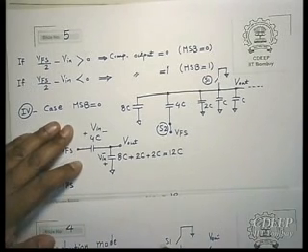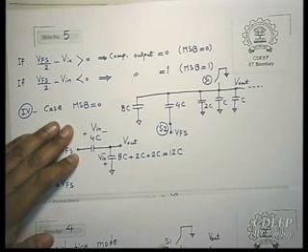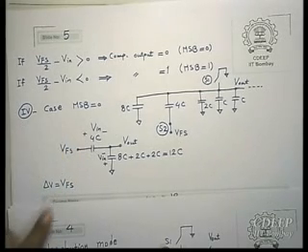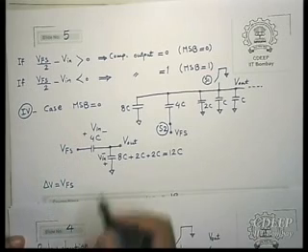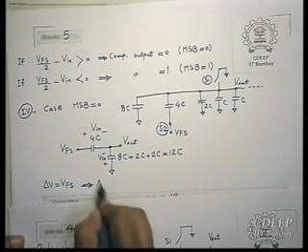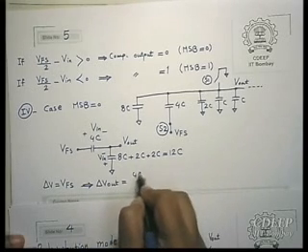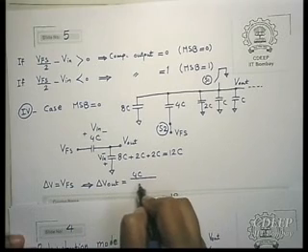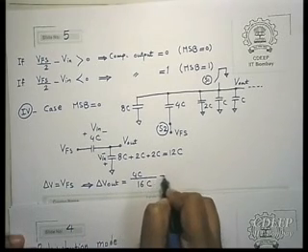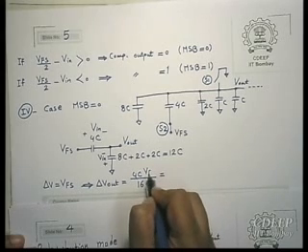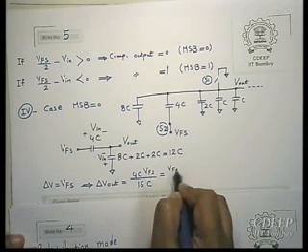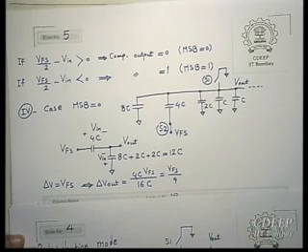Therefore, when you connect it to 0, the initial voltage has been 0. Now you are changing it by the amount of V full scale. Therefore, delta V out will be 4C upon 12C plus 4C, 16C, times V full scale, which will be V full scale by 4. So this is delta V out.